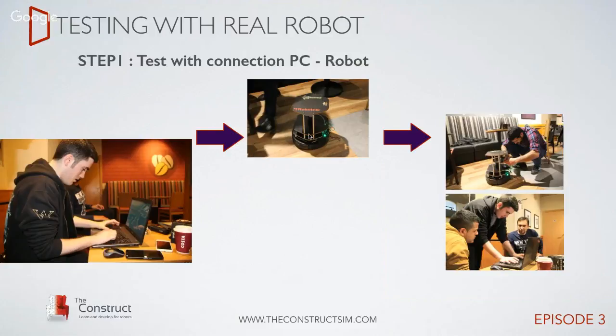Based on that result, maybe there will be some problem here or there, so you modify something in the robot. Maybe it could be something as silly as the laser detecting some parts of the robot that you didn't think about, so now it's detecting some parts of itself as if there was an obstacle in front of the robot. So you have to physically modify the robot structure.